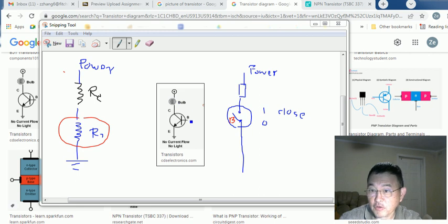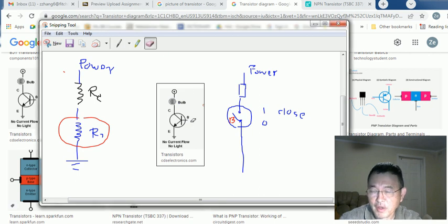But when the voltage over here is low, we mathematicians count it as 0, and then there will be high resistance, which means there will be no current. Electrically, it's equivalent to this circuit. If you have never learned circuit theory, Ohm's law, they're equivalent to 2 resistors. This light bulb is equivalent to 1 resistor, and here the transistor is electrically equivalent to another resistor.